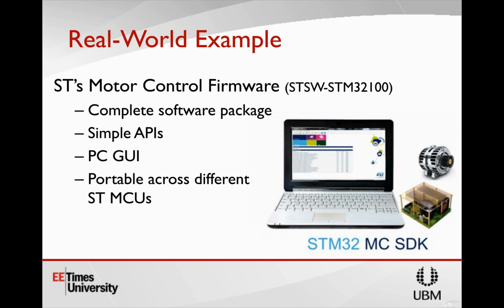Enrique, that's exactly right. What you would do is limit the output of your speed regulator. FOC is designed to make torque directly proportional to current. So by limiting the output of the speed regulator to an amount of torque or current, you limit the maximum current you're applying in your system. This is how you would do it: you limit it at the output of the speed regulator, before it enters the PI controller.